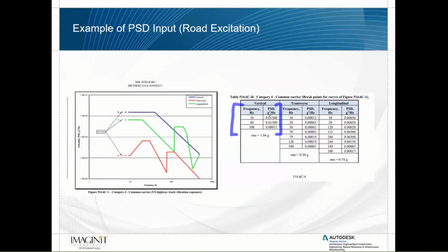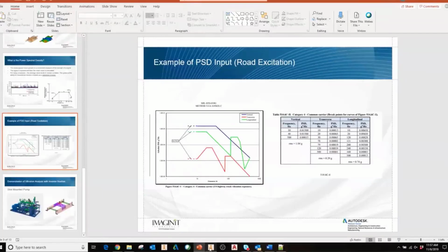I'm going to enter those three values into Nastran InCAD, and that is going to take my frequency response and scale it. So I'll be getting what's called an RMS output, a root mean square peak response. So we're going to be getting the statistically based summation of all of those inputs and getting a worst case scenario displacement and stress value.